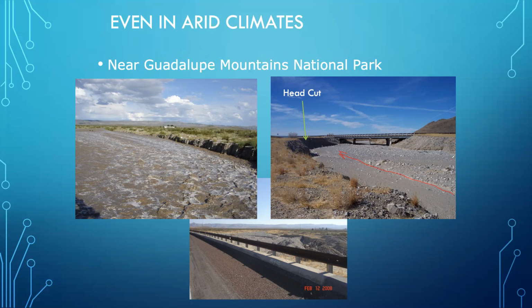The stream actually is supposed to be coming from here, but because of the way there's been earthwork in an attempt to protect both abutments of the stream, it's redirected to the point where it actually swings wide, and it's coming like that to make its way through the bridge opening.